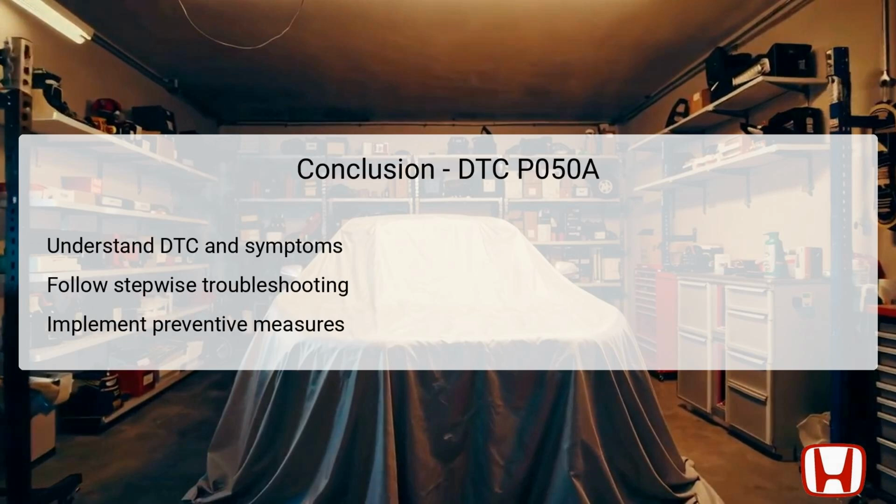In conclusion, understanding DTC P050A and its associated symptoms is crucial for ensuring the Honda Fit operates efficiently. Following a structured, stepwise troubleshooting approach can help mechanics pinpoint and address issues related to the cold start idle air control system effectively. It is essential to recognize the importance of component checks, such as the intake air duct, air cleaner housing, and MAF sensor.